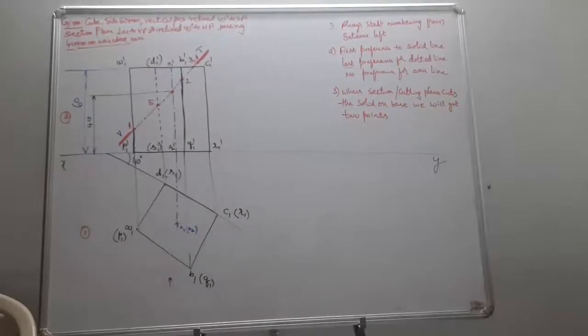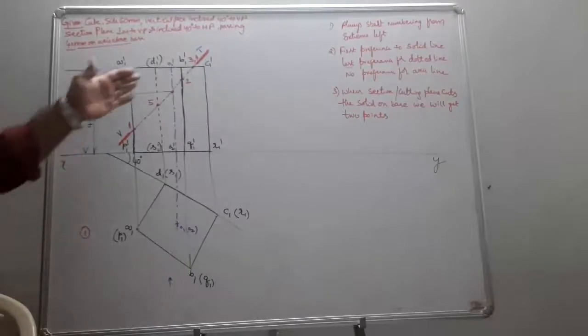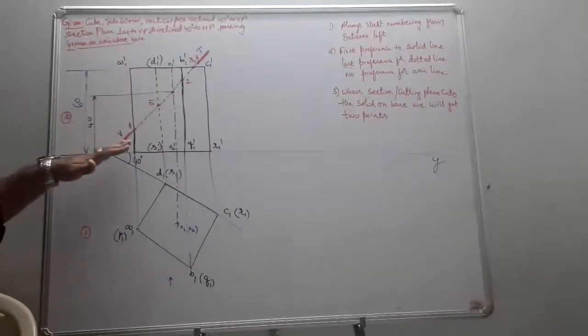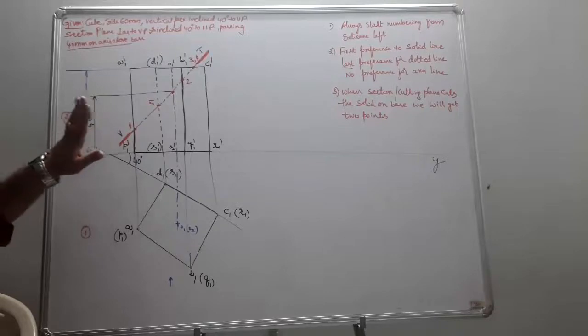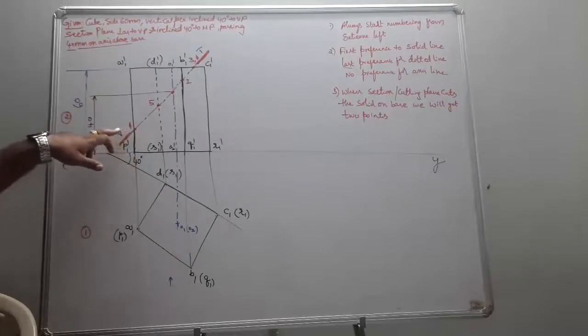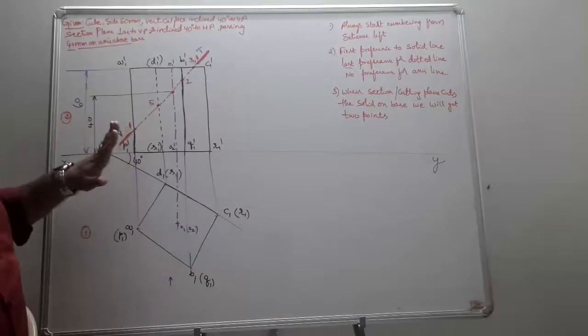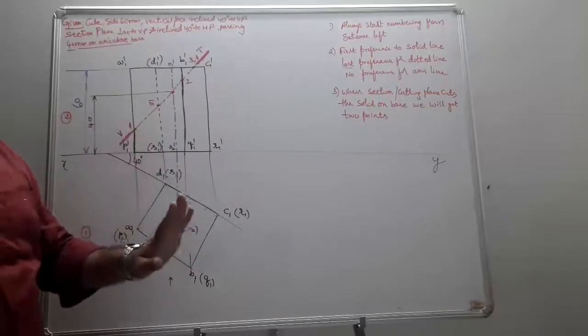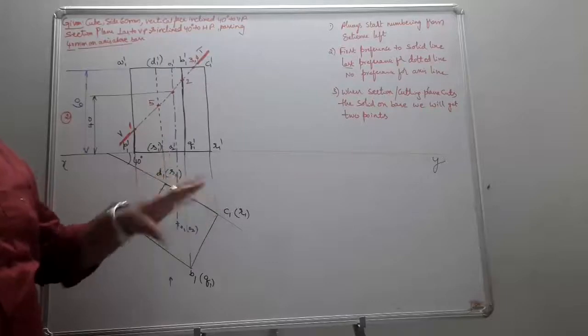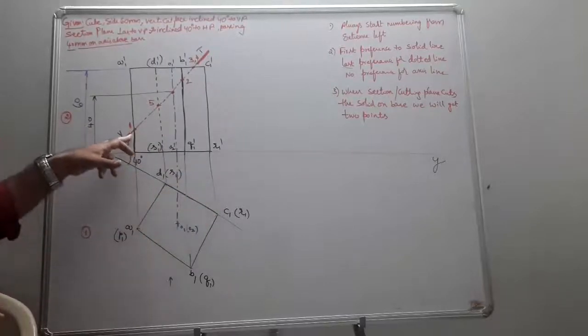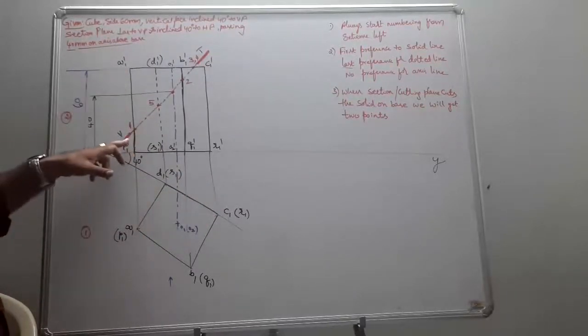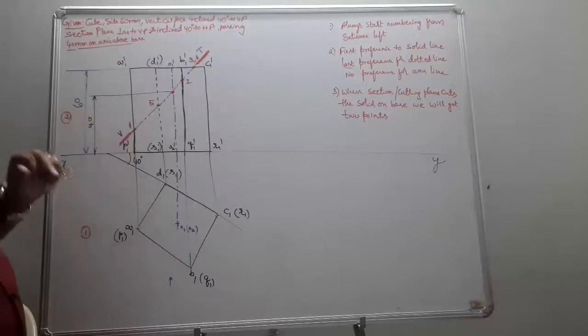All of you just see the points. First of all, I have written the points there. Always start numbering from the extreme left. What is the extreme left position? Wherever your cutting plane is going to cut your solid, I give the numbering there. Always give numbering first to the visible solid edges, next to the dotted lines, no preference to the axis line. The first point where it cuts the AP edge is point 1.